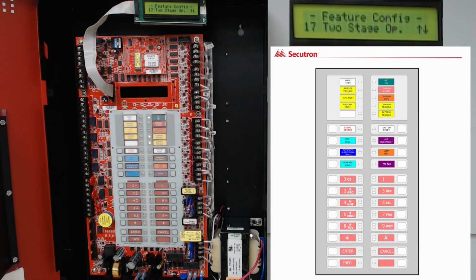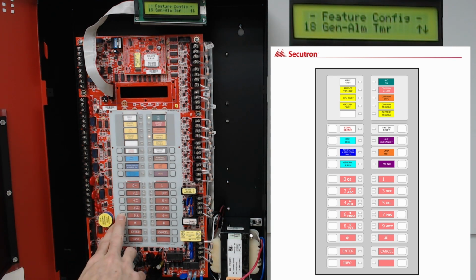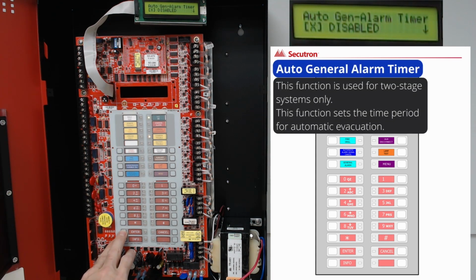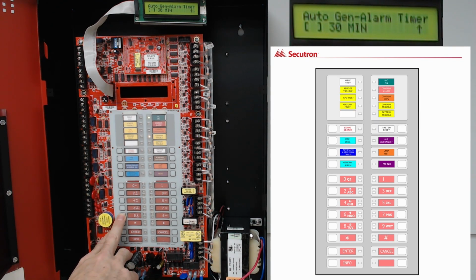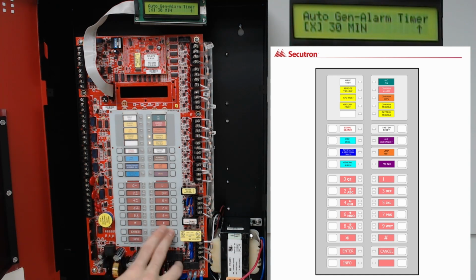The next option under feature config is general alarm timer. By selecting enter, we go into the options for general alarm timer. By default, it's been disabled. The other options we have are 5 minute, 10 minutes, 15 minutes, 20, and 30 minutes. When you find the desired duration for your auto general alarm timer, you can hit the left or right cursor, apply the X, and hit enter and cancel to exit back out to the previous menu options.